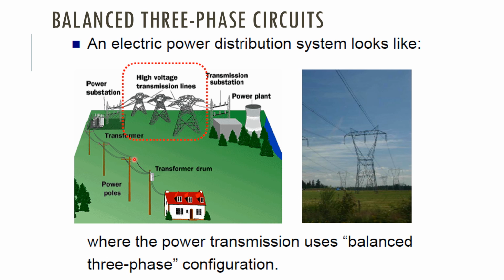Four wires. So there are three phases and one neutral. So normally for a house we take one live wire connection and we tap a connection from the neutral wire. In that way we load a single-phase system, right? Then we reduce into a single-phase system, but anyways it comes from a four-wire system.